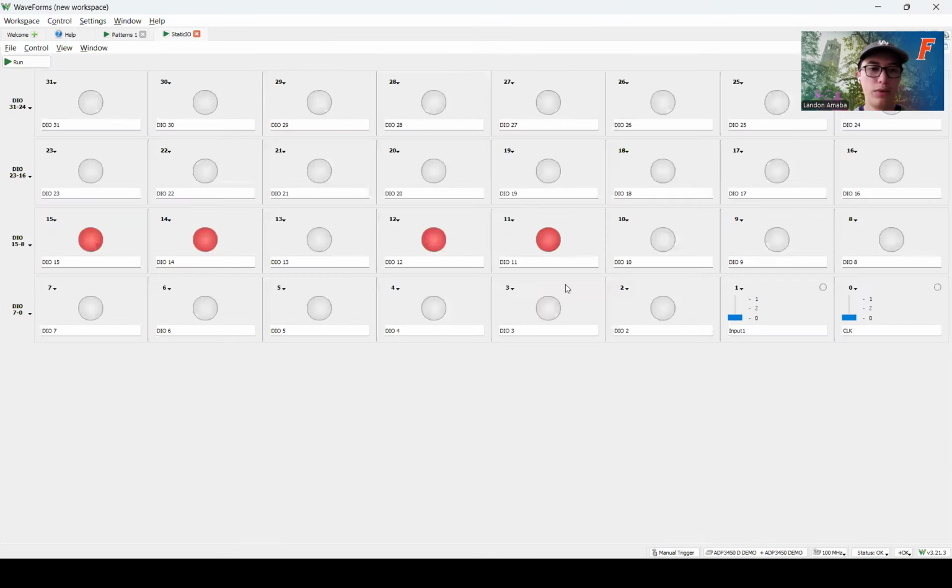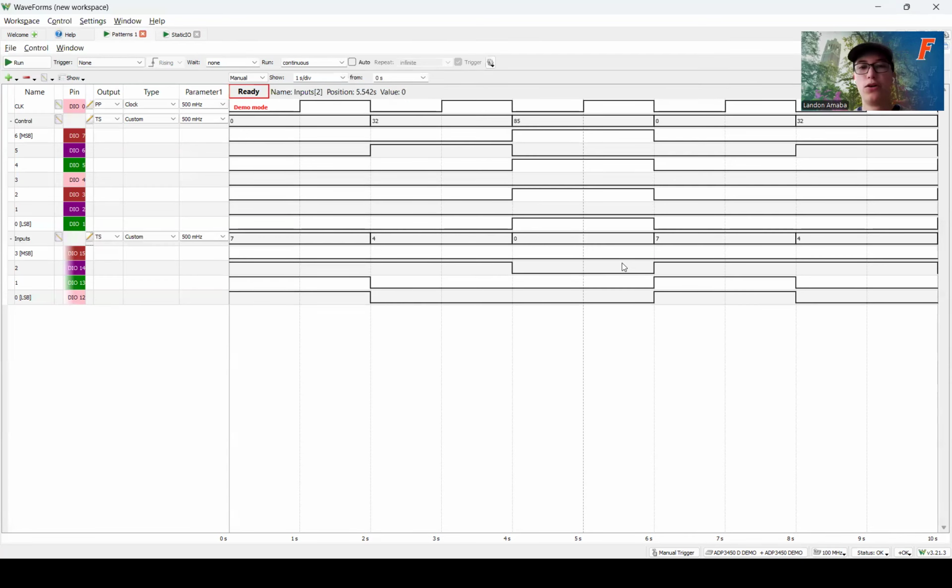So this is automatically feeding all these values into our system, so that now we don't even need the static IO, manually changing these and then clocking it when we're ready. When you actually implement this on hardware, you'll see the hex to 7 segments light up. It should go through your programs. You should be able to view register A and register B, as well as your output bus.